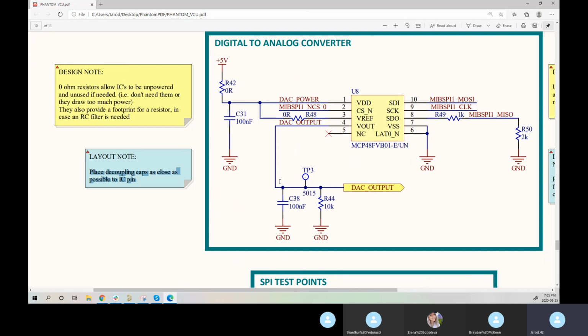So you know that your decoupling cap, you want to be as close, although you may not be able to show it in the schematic because of everything that's going around it. The component may be way off to the side, but you just want to make that note clear that you should be placing this cap as close as possible.